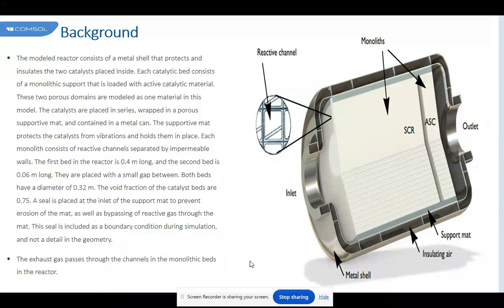However, according to this simulation, the computed fluid has a strong preference for the zone with the lowest cell count, regardless of the temperature. Despite the cell density of the ring monolith, the two cases with the 900 per 2.5 monolith in the core show higher temperatures than those with a core of 400 per 6.5. The thermal conductivity of the 400 per 6.5 substrate is approximately 30% higher than that of the 900 per 2.5 substrate. Hence, a more homogeneous temperature would be expected in that region.